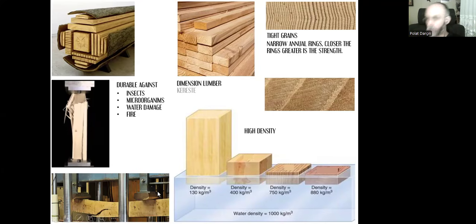And the rafters and the purlins, they are basically beams, so they will be under bending and deformation. They will be under these compression, and at the end of these compression loads, this upper part will compress, and the lower part, the molecules will want to be separated. That's what we call bending deformation. So for the compression, for the vertical pieces, and for the purlins and rafters, we need all these properties.